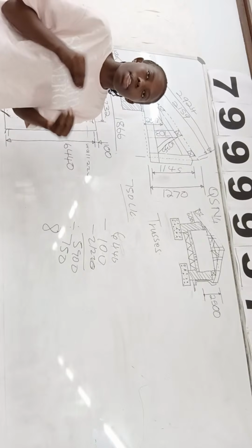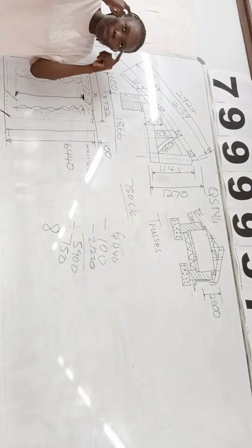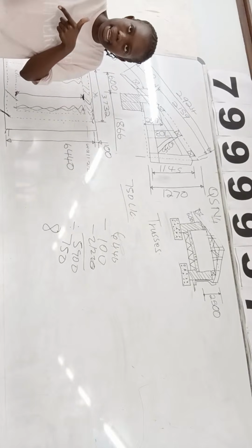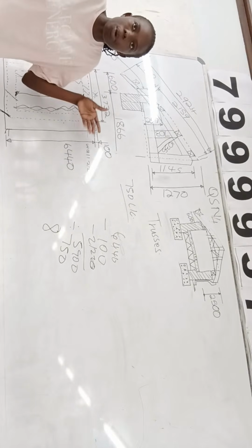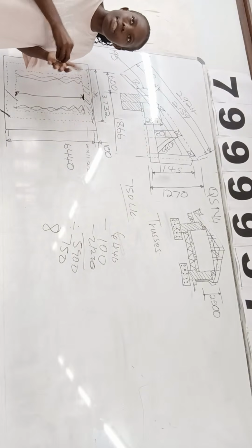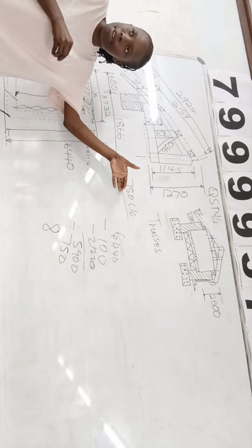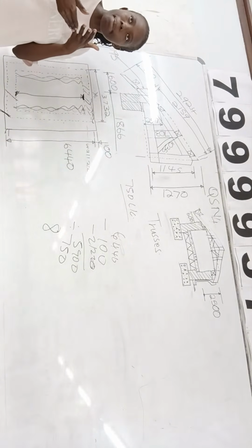Again, the number you get when you calculate, you're going to take the longest side. Keep in mind, I want the internal length. If I want the internal length, I take my length and then subtract my walls. Then I divide by what? The spacing, the center to center on the specification. And in this case, it's 750. Then I round off the number that I got.